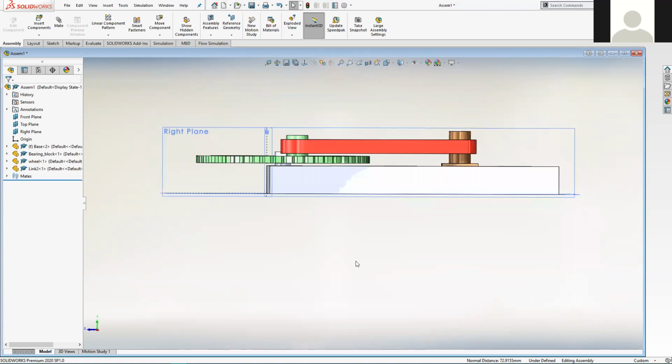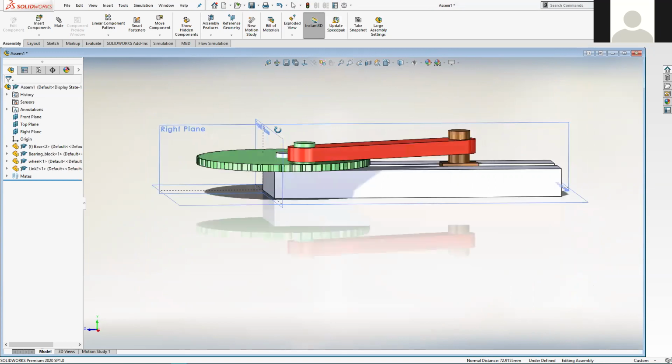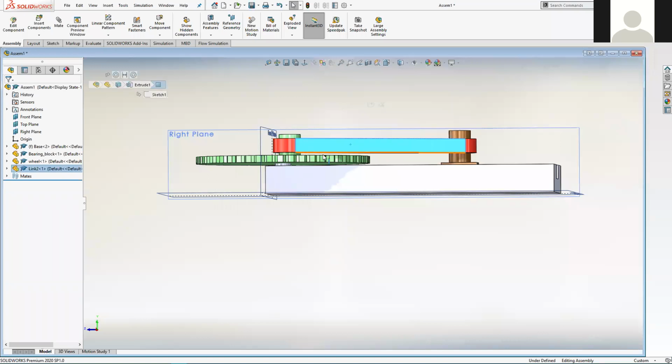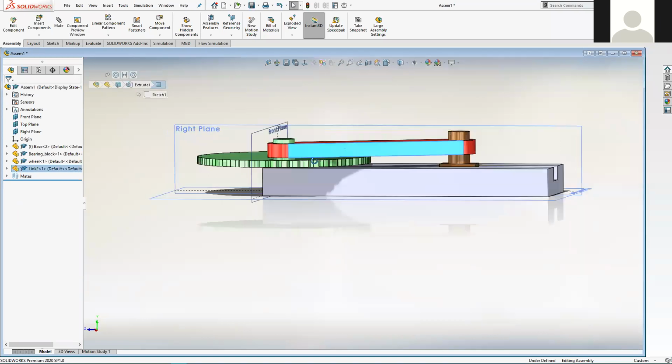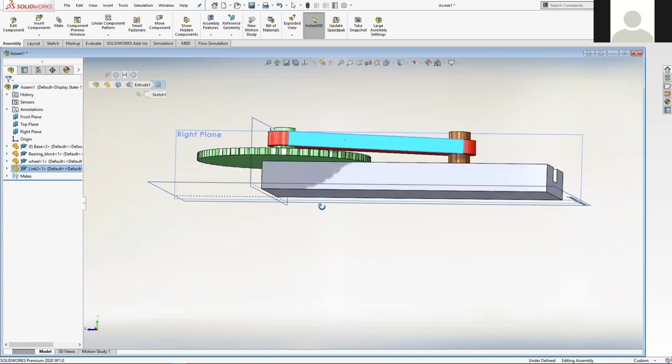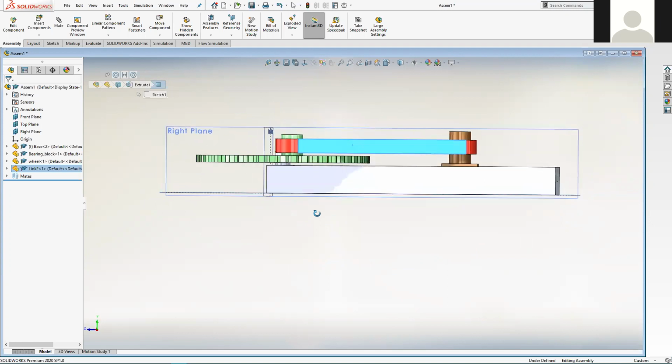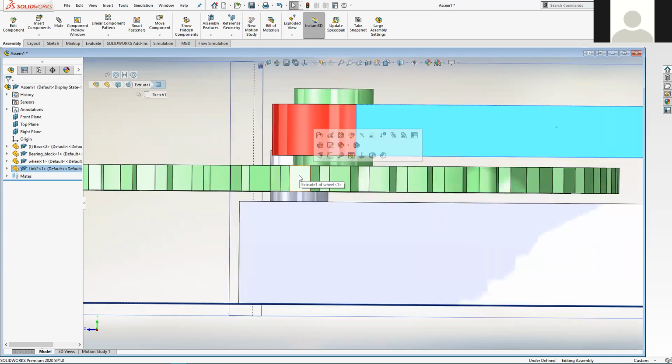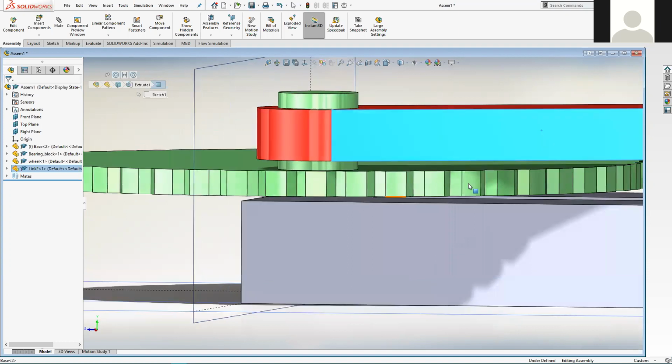So this is a moderately unrealistic kind of assembly. You would need some method of holding this link up against gravity. But given that I've already said, unless you switch gravity on in these simulations, it doesn't exist. So I'm assuming that this disk thing would drop under its own mass down onto that top surface there.